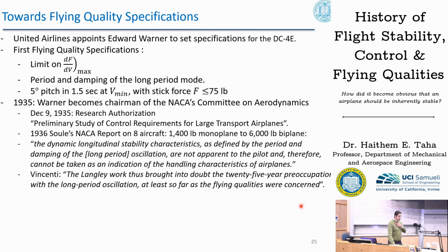Because the long period mode, as we discussed, is pretty natural. If you launch a model or a glider or an airplane, they all go through the long period mode. And when you see a mode as an engineer, when you see your device going through oscillations with small damping, your first reaction is to try to enhance the damping of this mode. So indeed, the community was occupied for about 25 years, as Vincenti mentioned, with the long period mode, trying to enhance the dynamics of this mode, but it turns out to be actually not needed, because any corrective action of the pilot would make it fine.